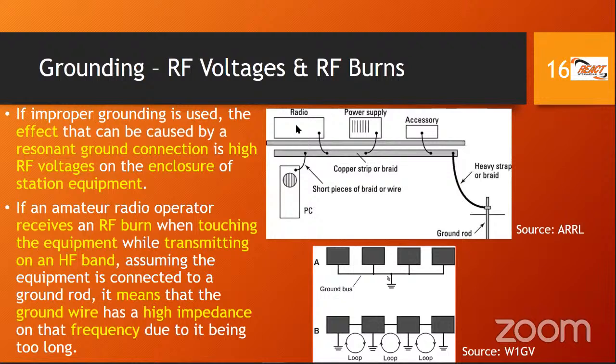So for example, this is your radio, and you might actually touch your radio or your power supply or something else, and if it's not properly grounded, you might get an RF burn, which is not nice at all. So you need to be aware of that.